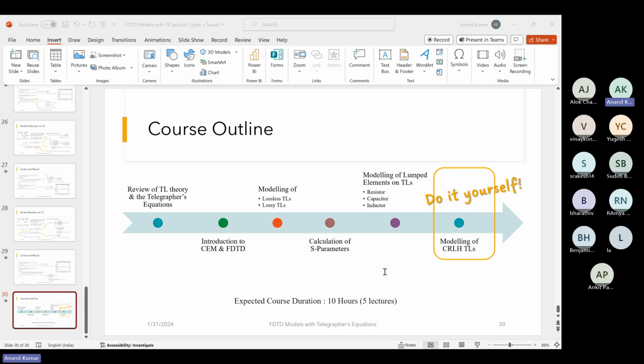Another technique is to use expressions given in papers. If a cube is half filled with dielectric, for example half with epsilon 4 and half with epsilon 6, we take an average of 4 and 6 and fill that value there. People have given different expressions for calculating how full the cell is and what value we should assign. So some sort of grading is done if a particular cube is half full.